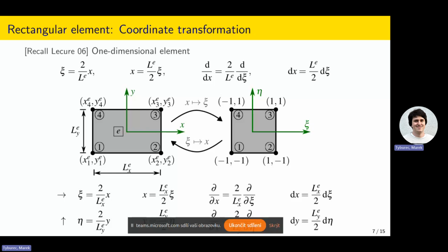And then these basis functions in this case, which you already did before, so I'm not deriving them again; I'm just writing them: N1 is 1/2 times (1 minus psi) and N2 is 1/2 times (1 plus psi).